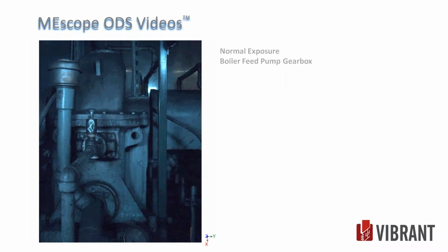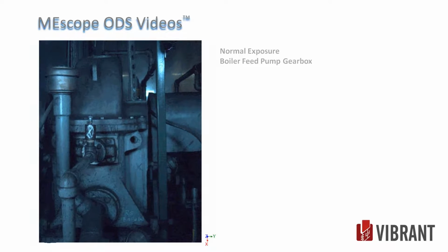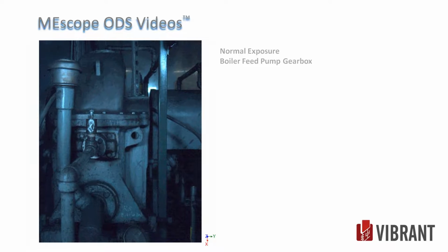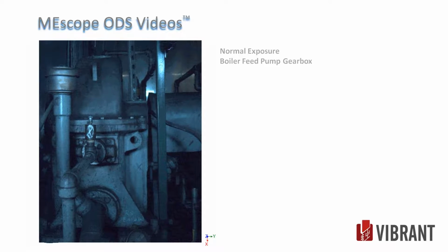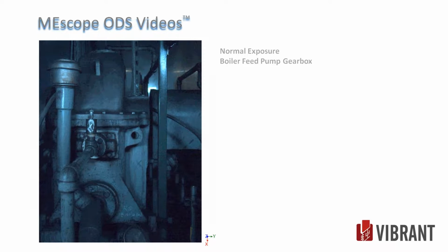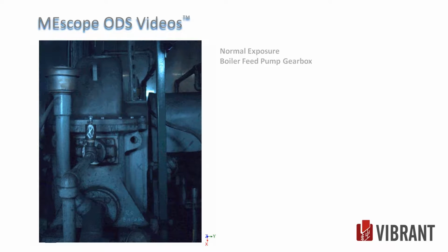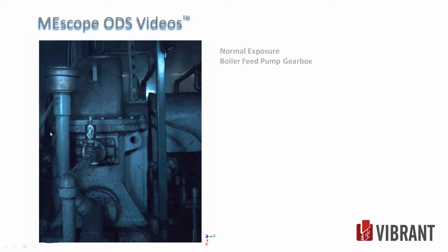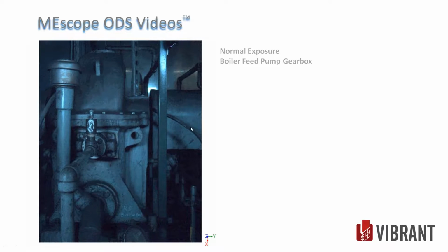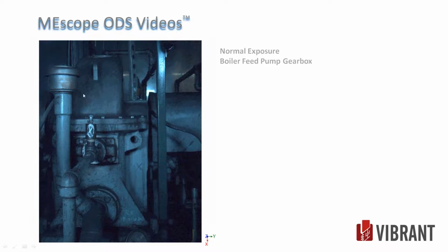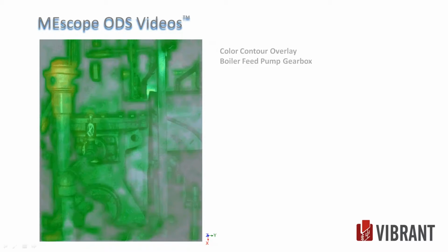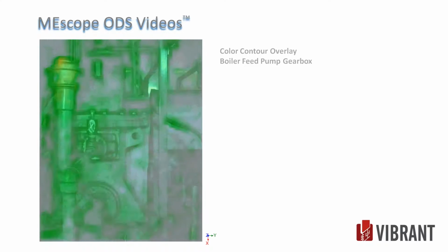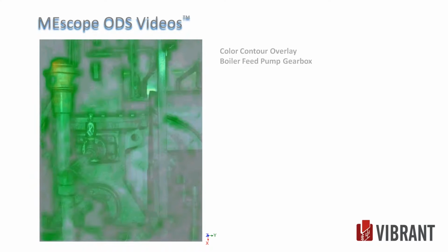This is the boiler feed pump gearbox. It's a system. There's a turbine, boiler feed pump, a gearbox, and then a boost pump on the end. So the whole system was doing the same thing. This feed pump gearbox, everything's in phase except this line flopping around. In the color contour plot, you can see it even better. Everything's moving in phase. So it's all moving with the deck.